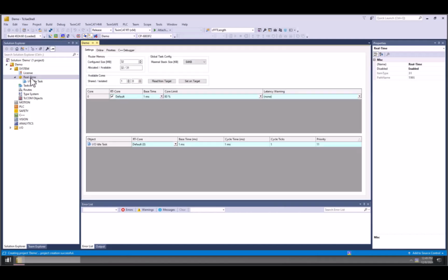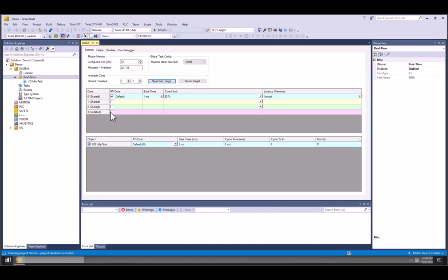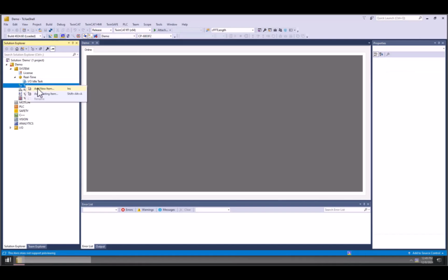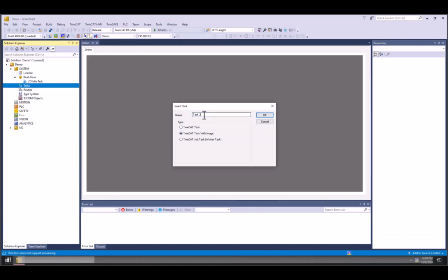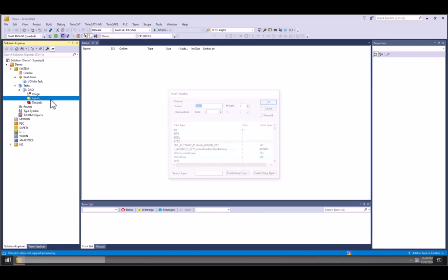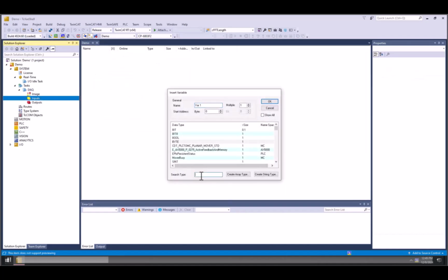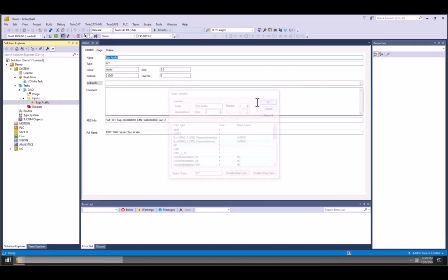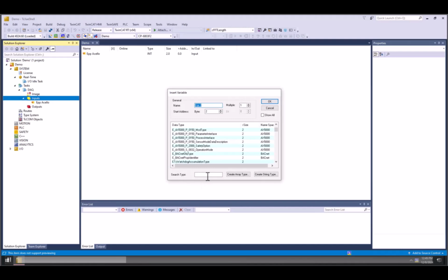First I'm going to set up the real-time setting. I want all of this to be on a specific isolated core that's running a task linked to it with no other interruptions. And I want to present a linkable array where I can land all of my measurement data as we're communicating it, not as each individual data point, but as an entire array of oversampled data.